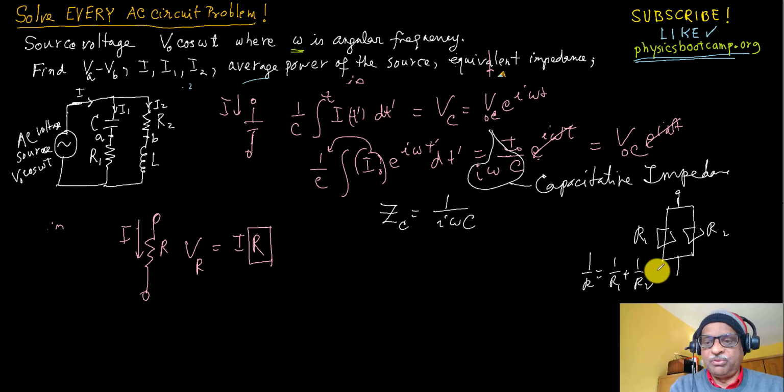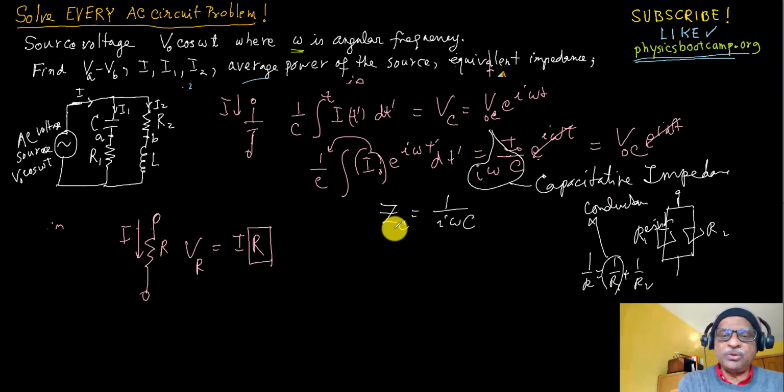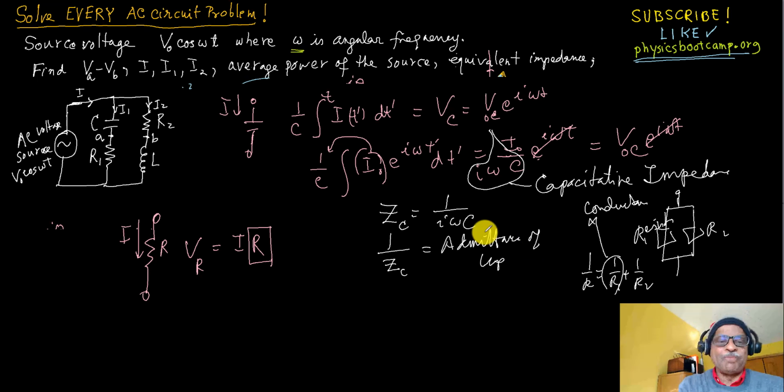You remember that from before, right? So the inverse adds, and the inverse of resistance is called, do you remember that? This is called conductance. So there is also a word for 1 over Z_C, which is the admittance of the capacitor. Okay, so these are some words. This is a complex thing, so in the analysis there will be complex numbers coming in.